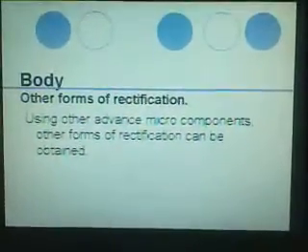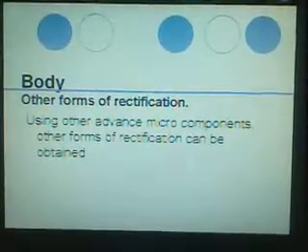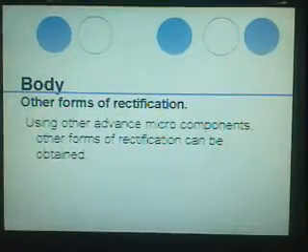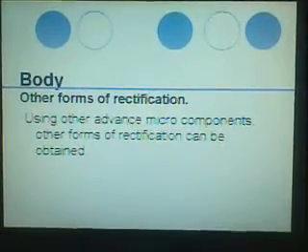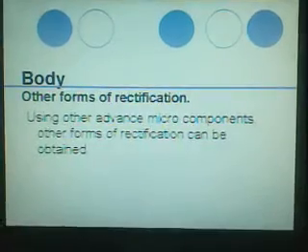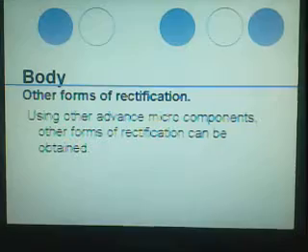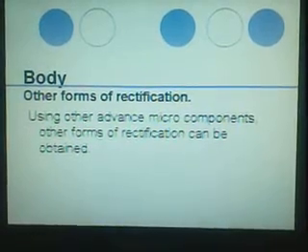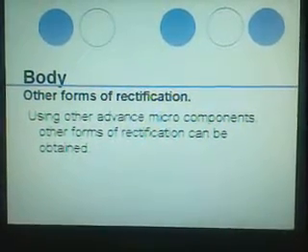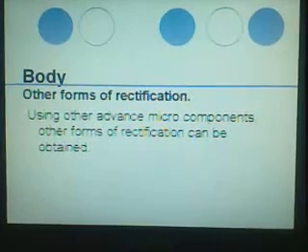I will be reporting other forms of rectification. Rectification is the process of converting alternating current voltage into DC. As it had been said earlier, the process of rectification is usually done with the aid of diodes, but there are other ways to rectify signals. It is with the use of precision rectification. This kind of rectification is a combination of operational amplifiers and diodes. Though it emits a smaller rate of amplification signal, it will be done with higher accuracy than the normal kind of rectification.